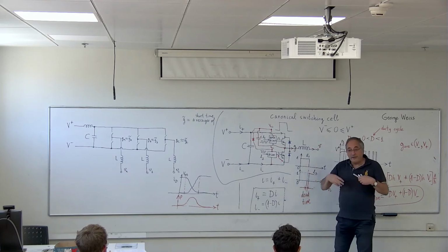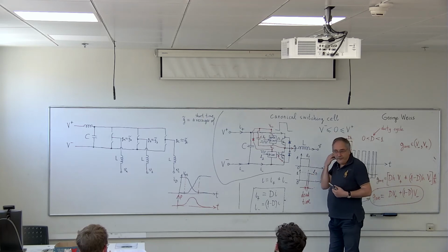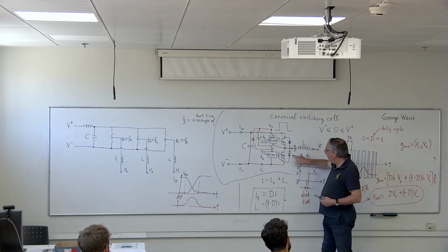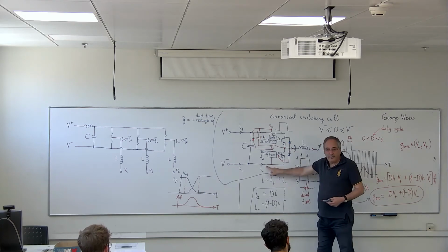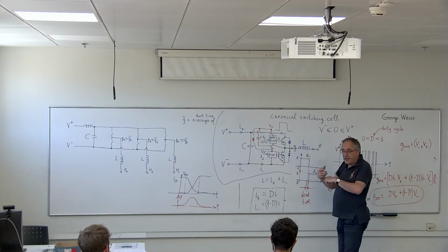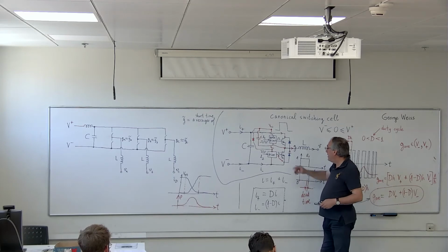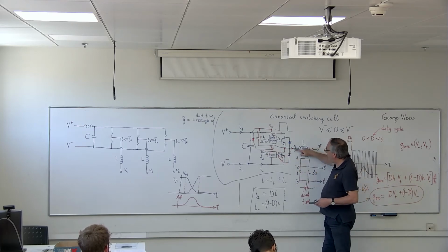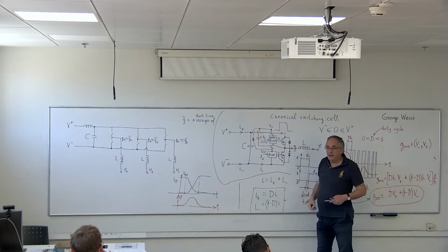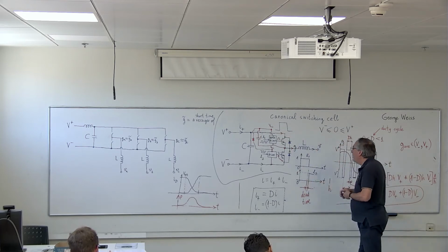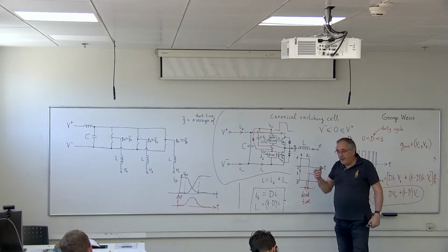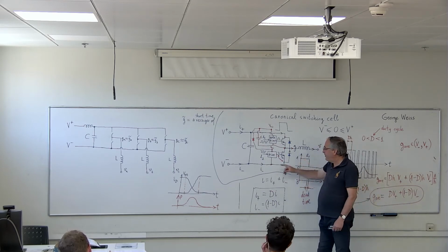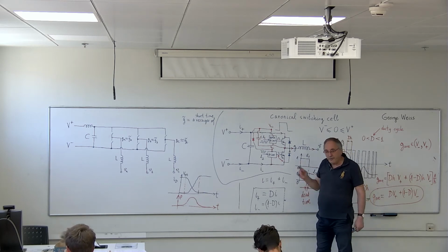Yeah. So when you are in the dead time, then in fact, from the point of view of the system, you are already connected to the lower voltage, to V minus, because now the current will come from this diode. So you are in fact already connected to V minus during the dead time. And the same in the opposite direction. Yes, if originally the current was coming from here, and now you are in the dead time, this happens when the current flows in the opposite direction. Then the current flows this way. Then when you disconnect from here, the current will already start flowing through the body diode to V plus. Okay, so the dead time is meant to protect the switches, but it is still true that the point G at any moment is connected either to V minus or to V plus. Even during the dead time, it is connected through one of the diodes.